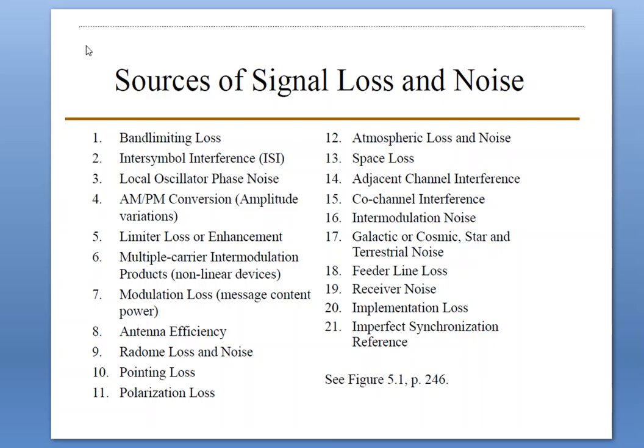This non-linearity generally occurs at the junctions of waveguides, coupling joints, and corroded surfaces, at surfaces having poor electrical contact. When large EM fields impinge on surfaces that have diode-like transfer functions, they cause multiplicative products and hence noise. If such noise is radiated into a closely located receiving antenna, it can seriously degrade the receiver performance.